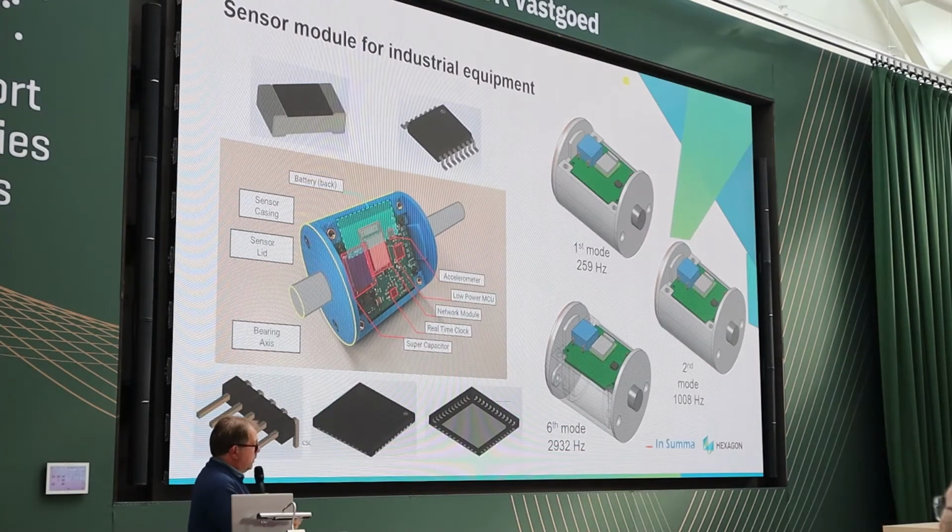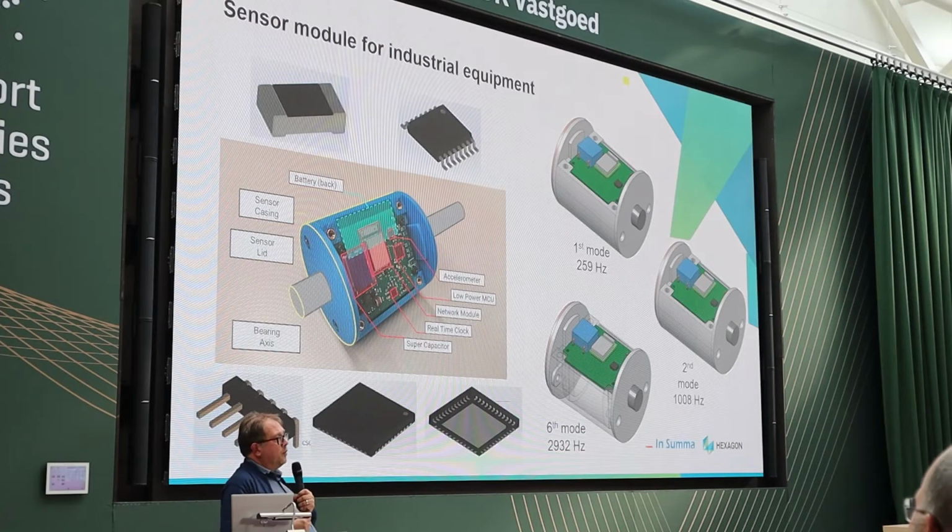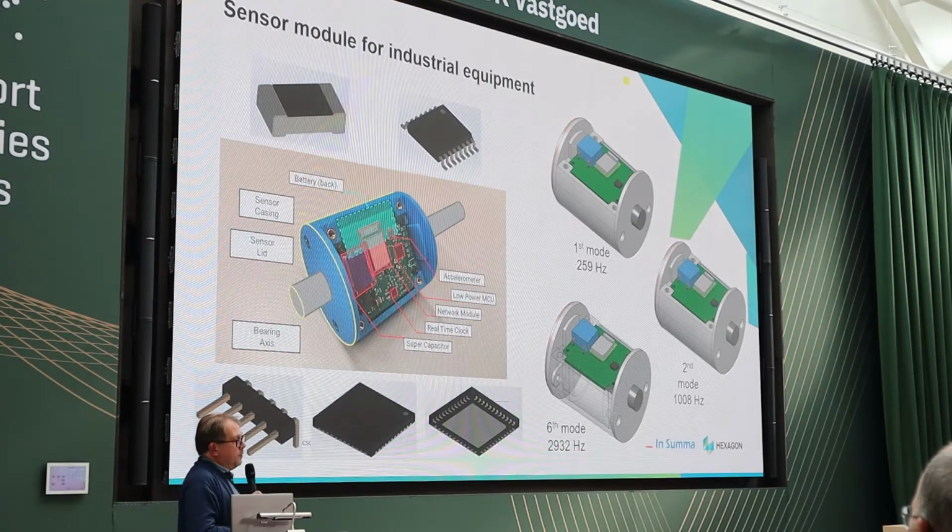The scope was harsh conditions. It is mainly industrial equipment, so there are a lot of mechanical vibrations, and you don't want this sensor to be damaged over time due to these vibrations. The first thing you look at is the eigenfrequencies, to see if they are above the range of frequencies applied to the structure.